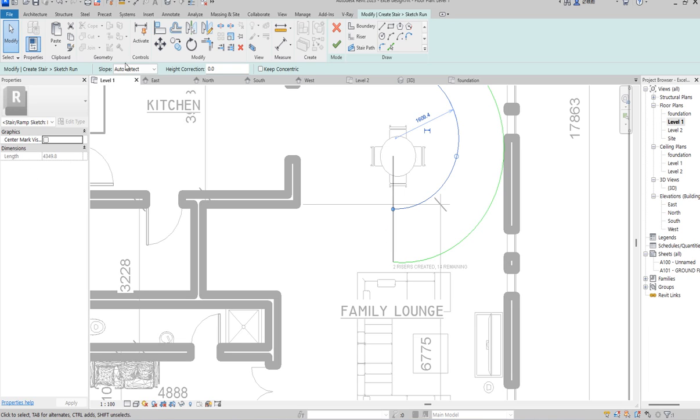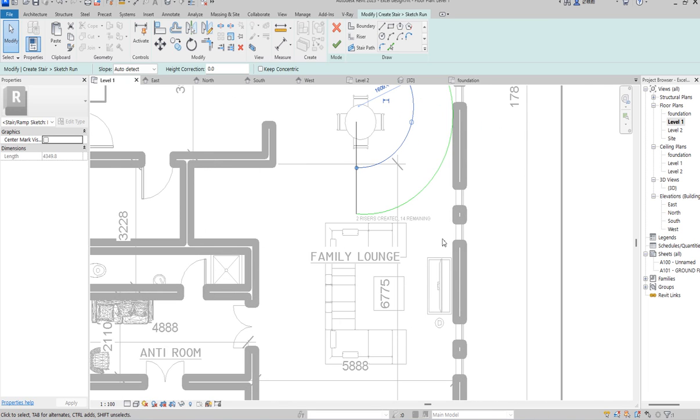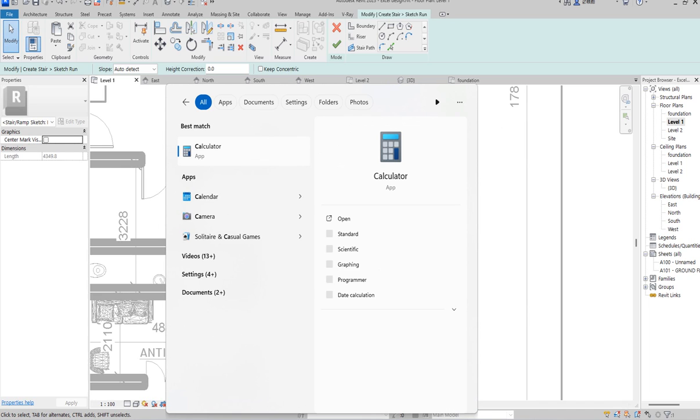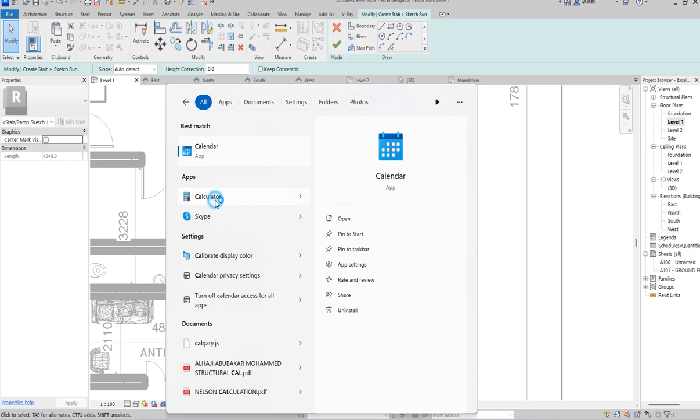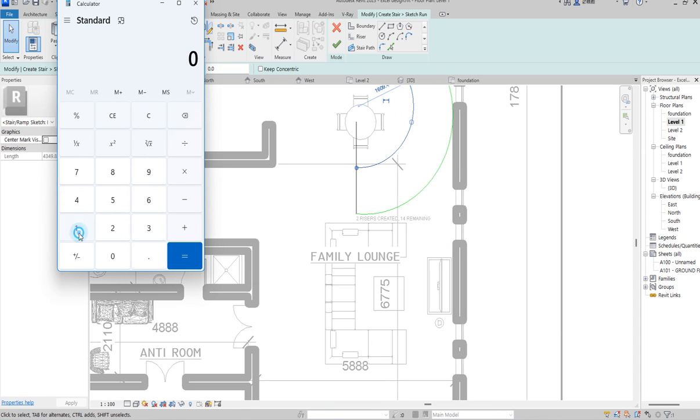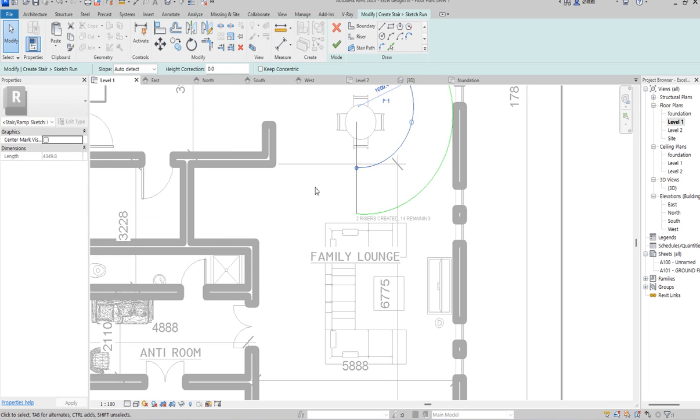So you have 12 degrees to work with, not 15 degrees. So let us try to work with 12 degrees and see how far we can go. And that is 14. No, I think there's an issue. Calculate 14. I have 180 degrees divided by, let me use 18 staircases. So with 18, that is 10 degrees. Yes, 10 degrees can do. So 10 degrees is what I'm going to use.